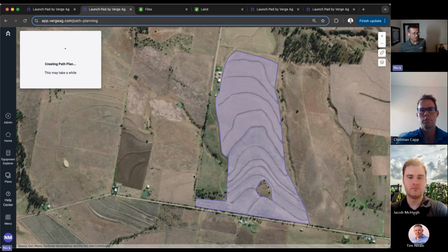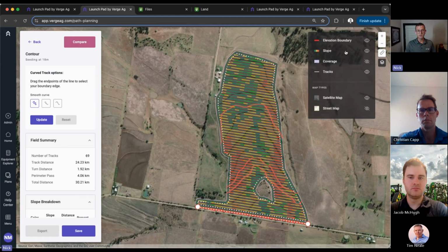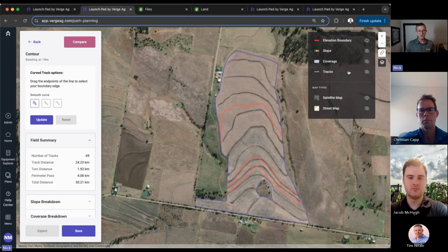And we're going to take that terrain model and build some contours for that. So I'll turn that off. And you'll see here that I have these contours that I created that mimic what's underneath there, because those are the real contours that they have.